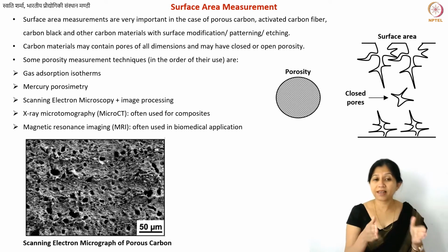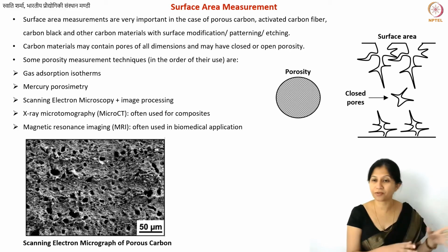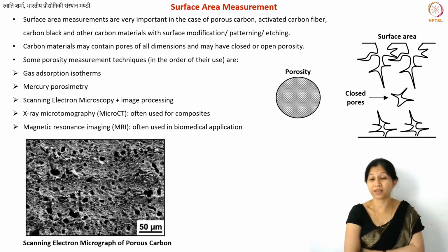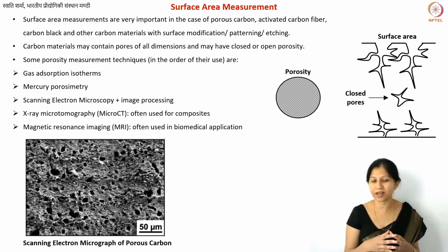But with this image, you can plot your own histogram. You can also perform the image processing using some software that is available nowadays. There are a lot of free software. So you can just upload your image and calculate the porosity. But that is something I don't recommend, not just for SEM or image processing, but for anything. Even with gas adsorption isotherms, you have an equipment, you upload your sample and you may get some numbers from it.